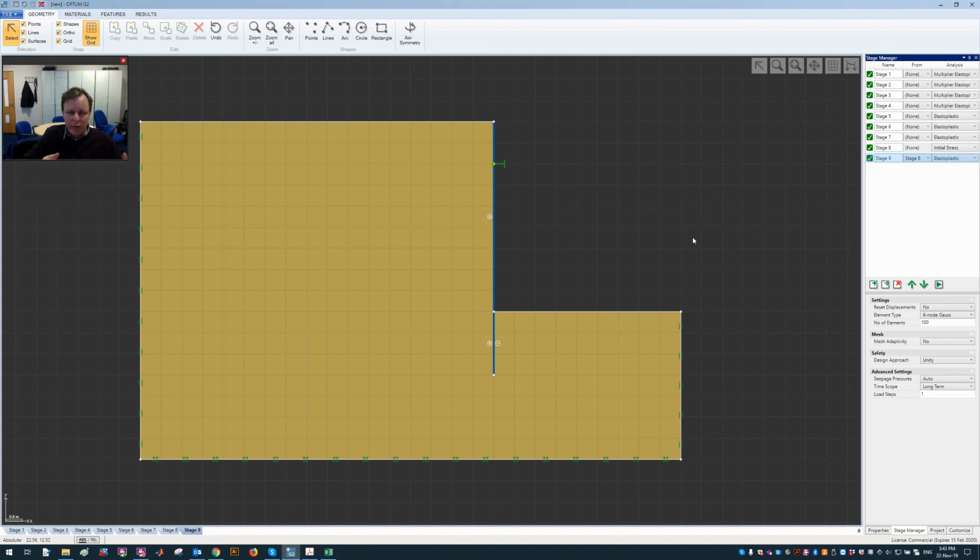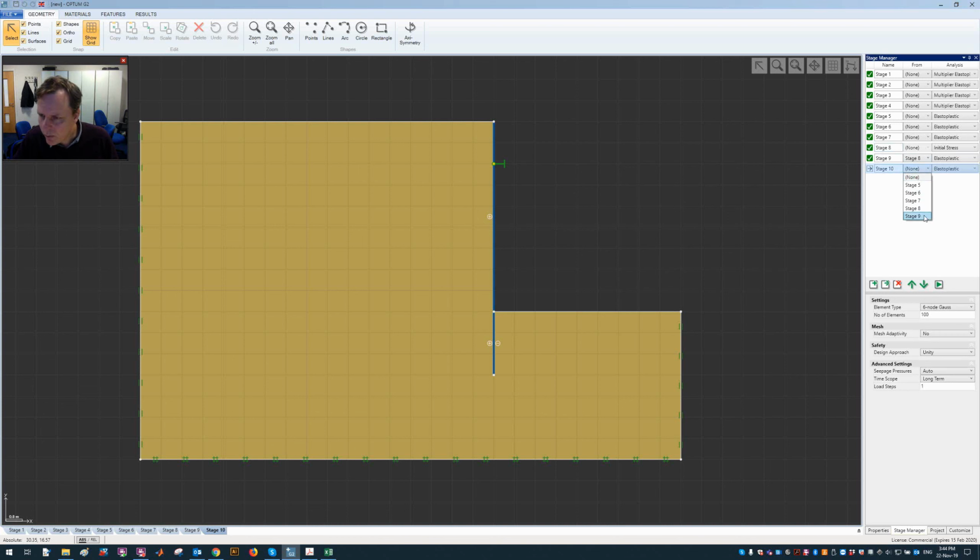An excavation is removal of material. It's not somehow a gradual and uniform reduction of the residual forces that we have to start with when we have just transitioned from one stage to the next. So it's a waste of time to use more than one load step, and the result you get at the end of the day is, in all likelihood, going to be a bit different from what you get with a single load step, but not necessarily more correct. The only way to really ensure the correctness of these types of stage construction is to have a more gradual transition of the geometry between the stages. But just out of curiosity, what would it mean to use 10 load steps here instead of a single load step?